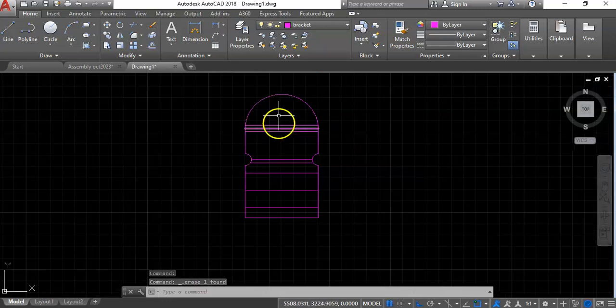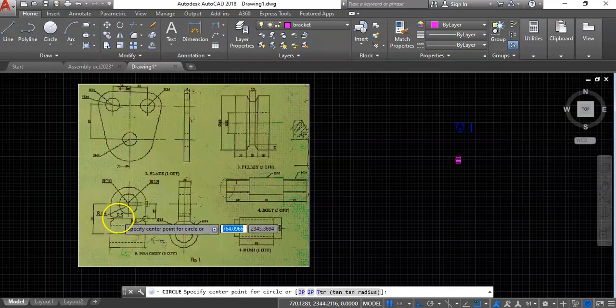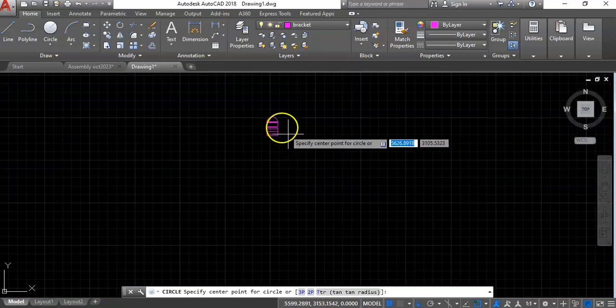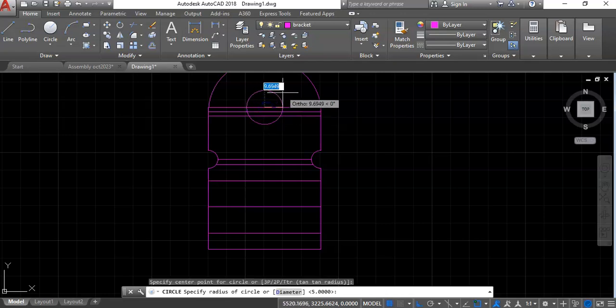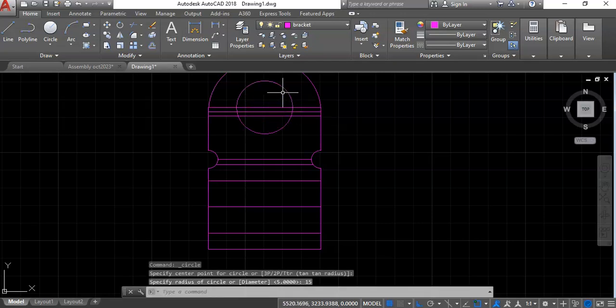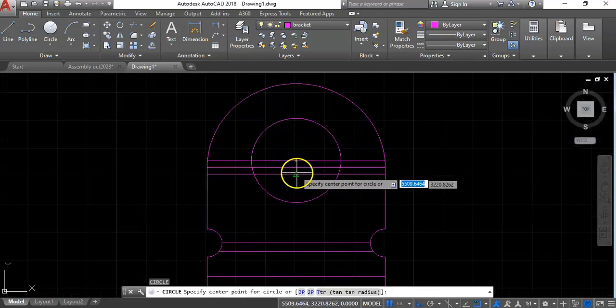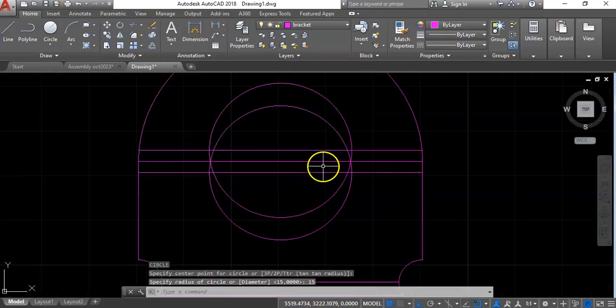So now next is to come up with what is here. So I'll go to circle radius. What radius do we need? We need a radius of around 15, but I feel 15 would be very okay. Let's try a radius 15 and see what happens. So 1 on top, we'll do 15, enter, then bottom here, another 15, enter.